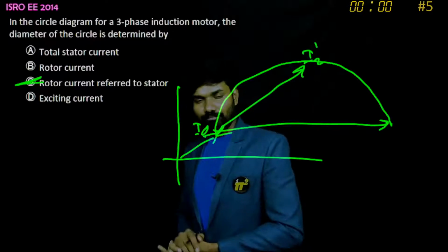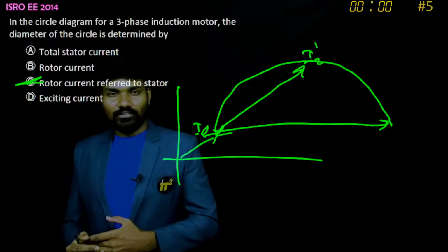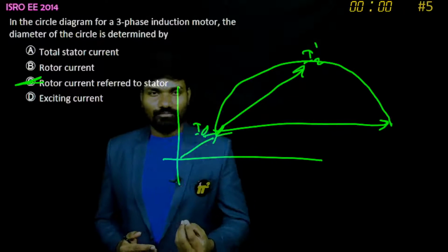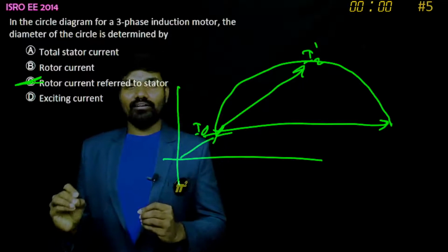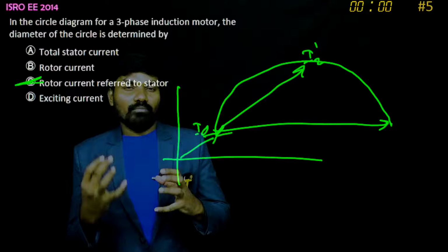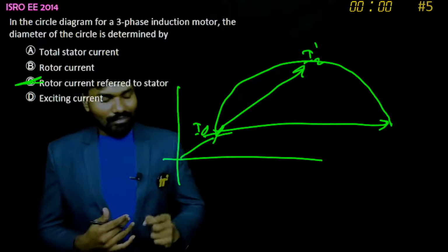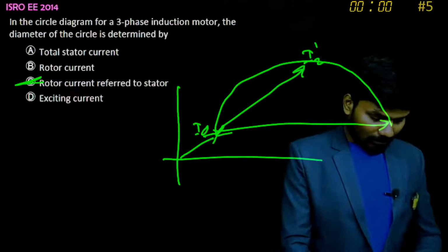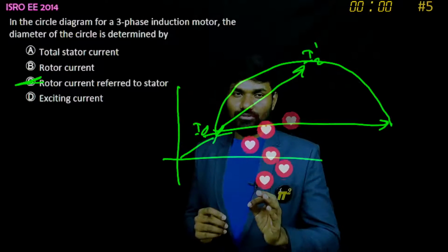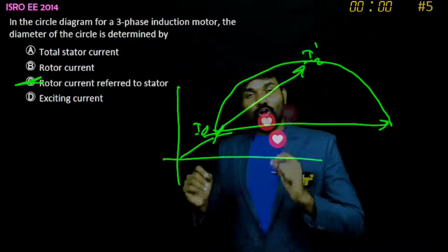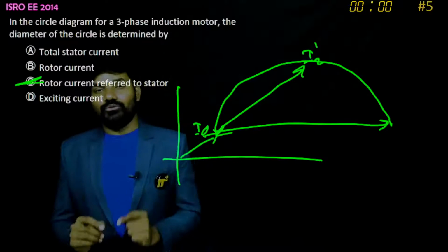And there is one more interesting point, what is said by Sampath. Sampath was saying in the chat, RMS will still produce. Sampath, I think slight correction. You're trying to say maybe RMF, rotating magnetic field. And we have a beautiful animated video on creation of RMF, rotating magnetic field. And to say a point, you're absolutely right. Yes, RMF will still produce, but not with a constant speed and not with a constant magnitude.